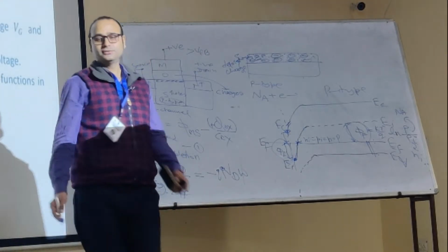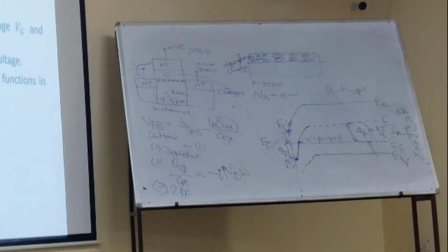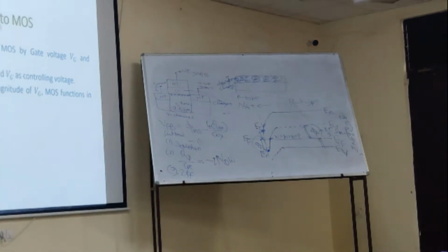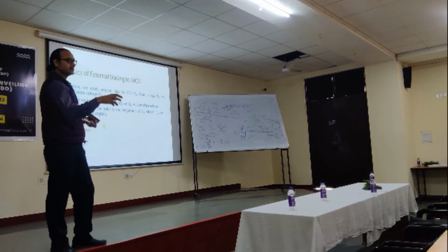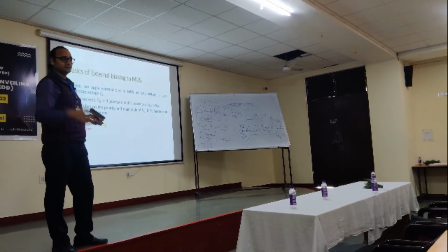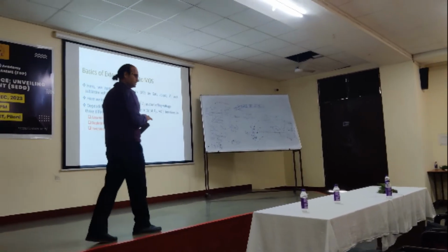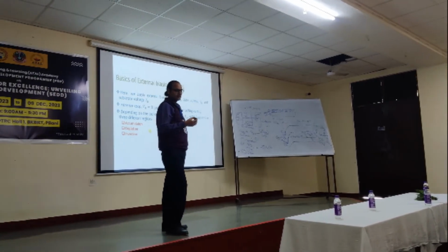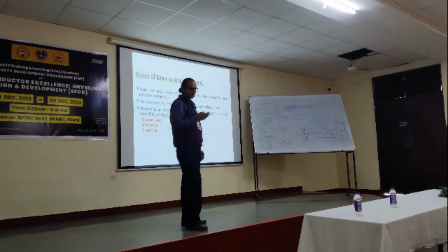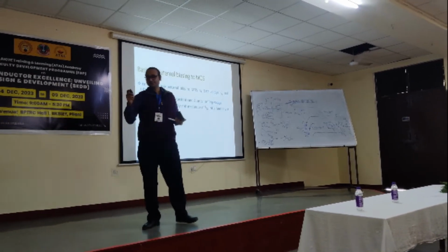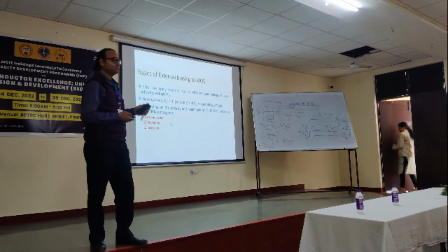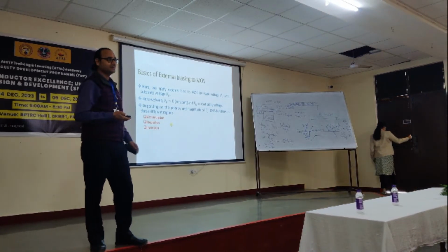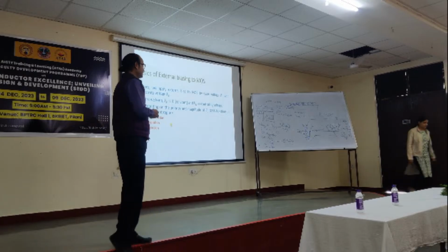Well, that's how we arrive at the derivation of threshold voltage. Flat band voltage plus the oxide charge term plus the depletion charge, and then 2 phi F. That much voltage is required at the gate. I hope some of you might have got that concept. I'm sorry that it is difficult to make these things understood, suppose people are from a computer science background, then that is very difficult, I guess. Okay,